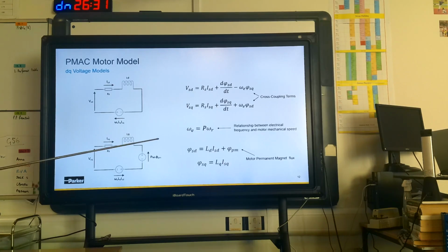There's then another equation down here that shows it's a synchronous machine. So the electrical frequency is glued to the mechanical speed or frequency by the pole pairs of the motor. If you remember the previous picture, the spoke wheel design had like 12 magnets arranged as spokes, so it was a 12-pole motor or 6-pole pair. Whereas the V's, there were 6 of those, so that's a 6-pole motor of 3-pole pairs, and that P there is the number of pole pairs of the machine.